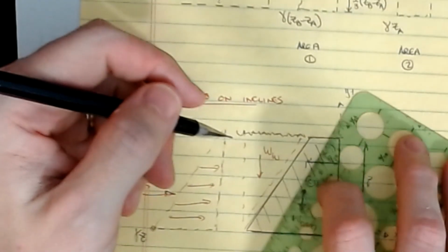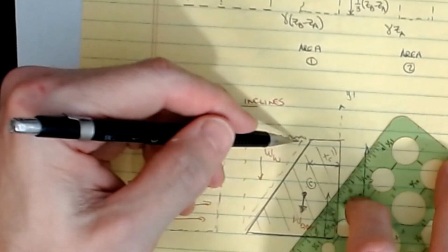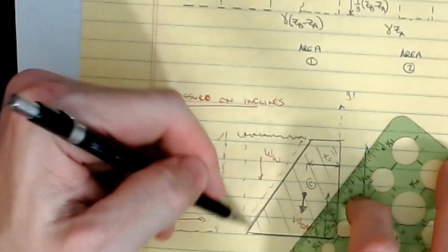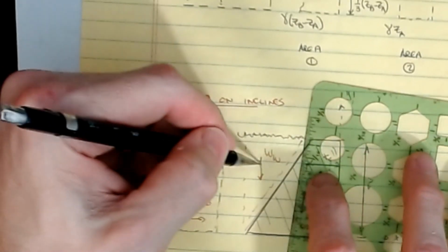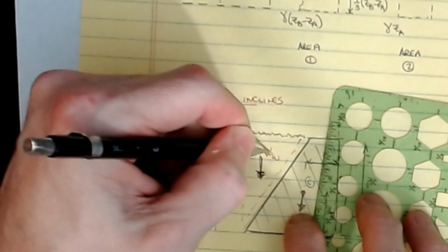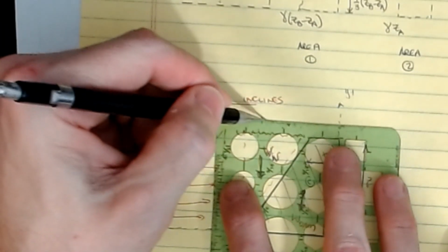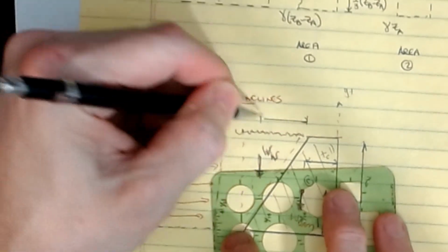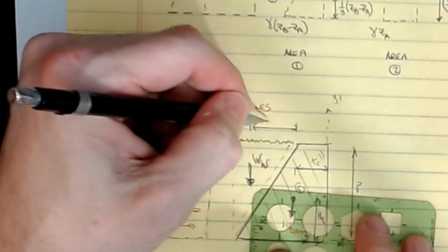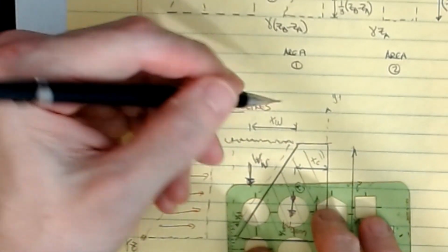The other piece we have is another load component. Because of the slope of this wall, there is a load that acts directly over that surface. It's the weight of the piece of water acting on the wall, which we call W sub W. Depending on the height and the dimensions, it's located at some XW value, relative to, say, this point.